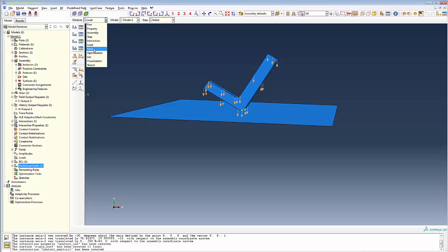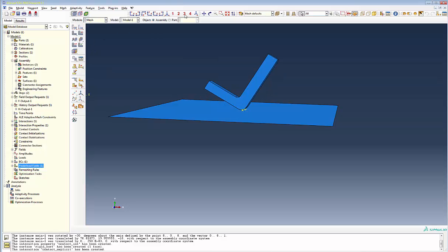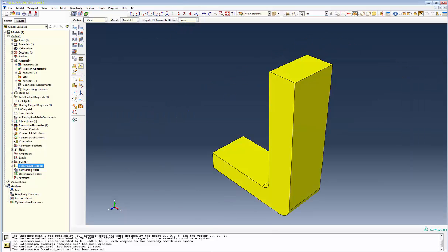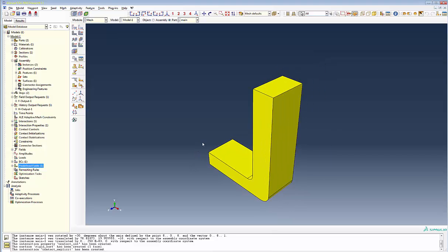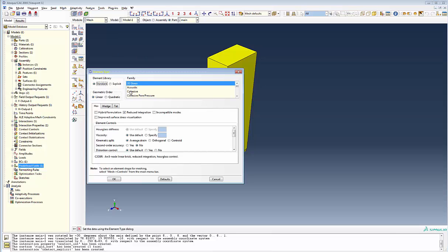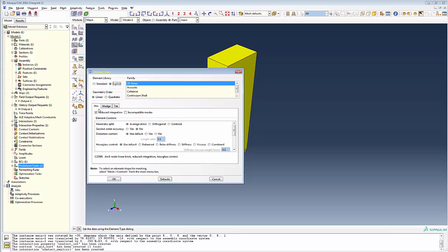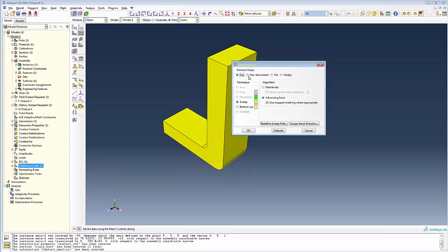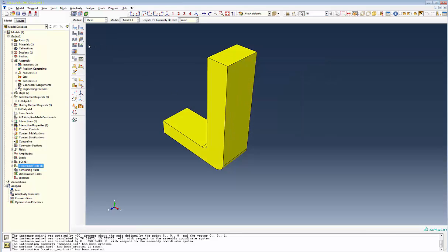Now we'll go ahead and assign the mesh, and the mesh obviously assigned to just the main part, and from the color it should be clear to you that the program thinks it can do sweep meshing. We'll go ahead and assign element type, and that's going to be explicit element. Don't forget that one. Hexahedron reduced integration is default. Let's just accept that for the time being. And then element shape is hex. Sweep meshing, as you're suspecting.